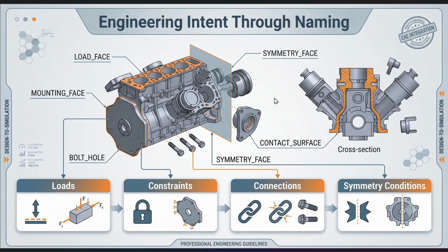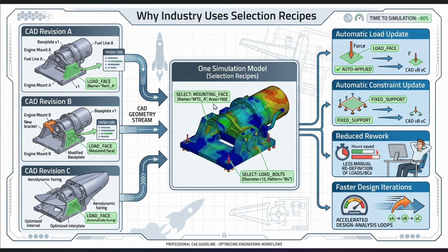And the third reason why this is used is robustness. Robustness means you're not trying to solve a model of today. You have today's model, it will survive today's conditions and cases, but there will be multiple design iterations, multiple studies, and your model will be changed. There will be CAD revisions, revision A, revision B, revision C, because you're always improving it. Now your idea is to make your assembly, make your simulation consistent with the CAD model, and make sure that your model is capturing everything, it doesn't matter which revision.